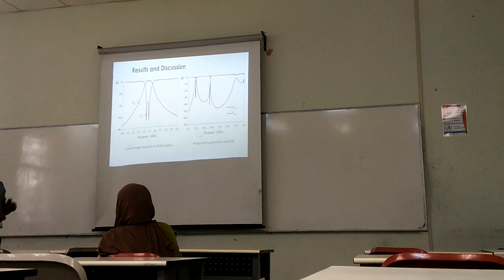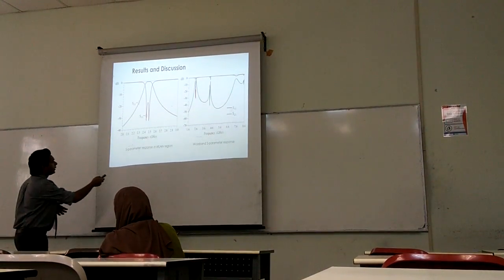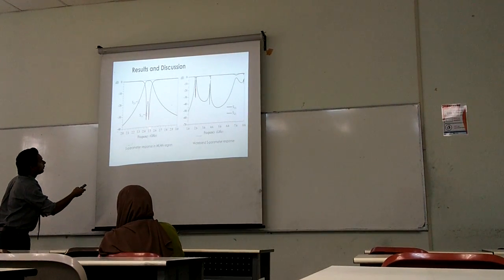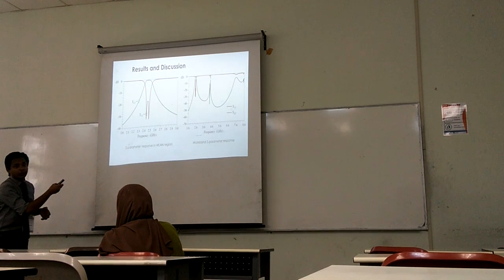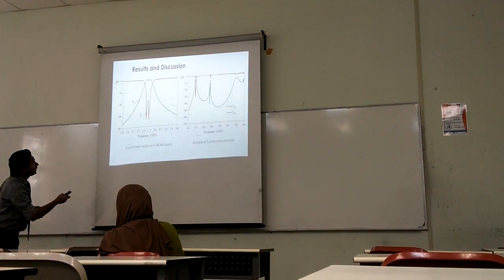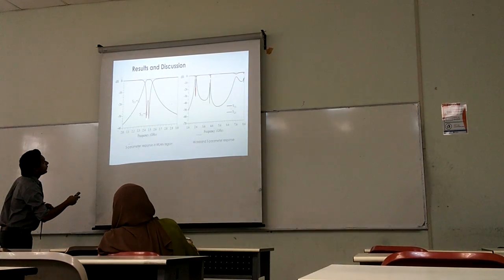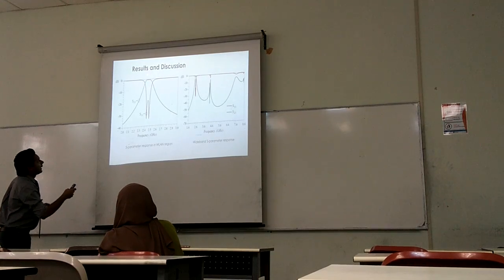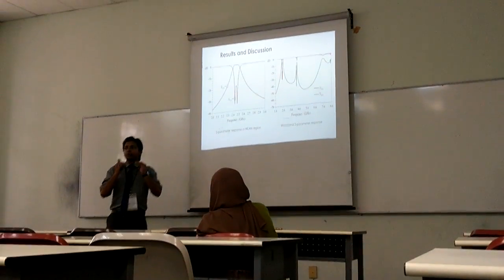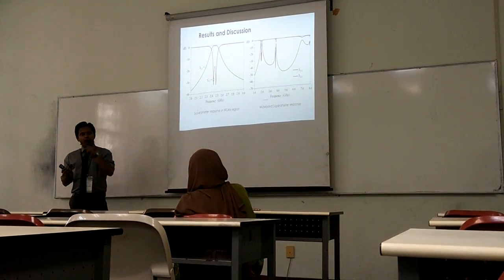And then let's look at the results of the performance of the filter. Our target was from 2.4 to 2.5, which is 100 megahertz. This is the 3D magnetic, as you can see. It sharply selects the WLAN frequency. And if you look at the center frequency, it's 2.45 exactly. And the most interesting thing is, as we have targeted to achieve a maximally flat response, because for Chebyshev response, we know that there's a ripple on the top.